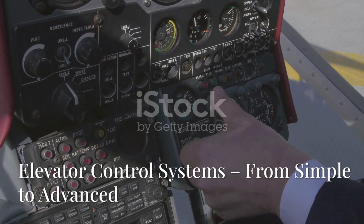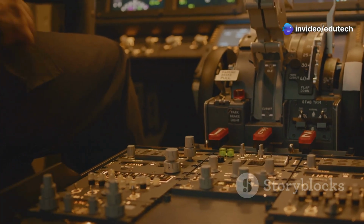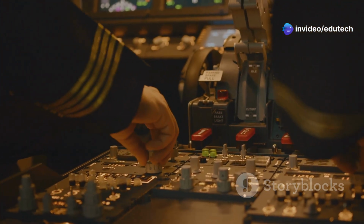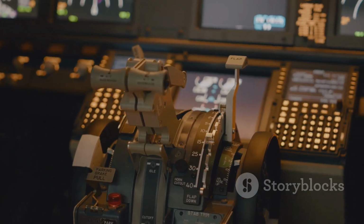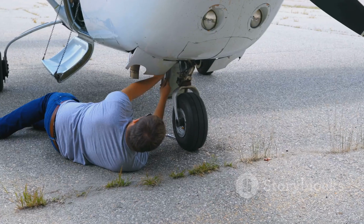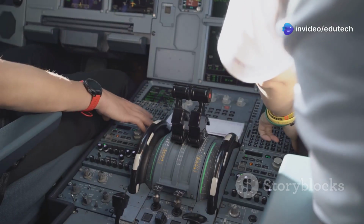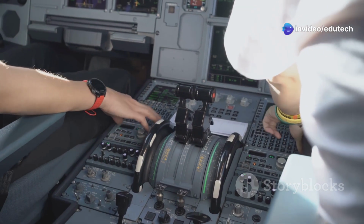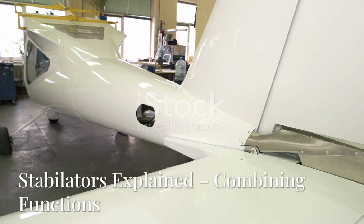Light aircraft use a system of control cables and pulleys or push-pull tubes to transfer cockpit inputs to the movement of the elevator. High-performance and large aircraft, on the other hand, typically employ more complex systems. Hydraulic power is commonly used to move the elevator on these aircraft, and on aircraft equipped with fly-by-wire controls, a combination of electrical and hydraulic power is used.